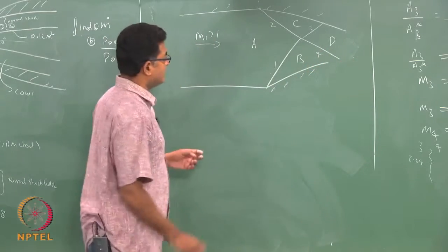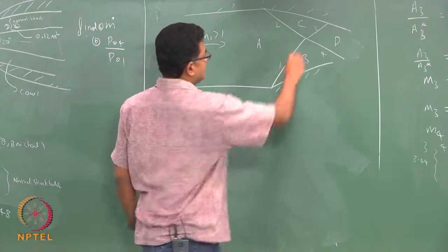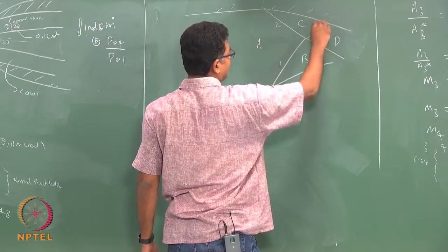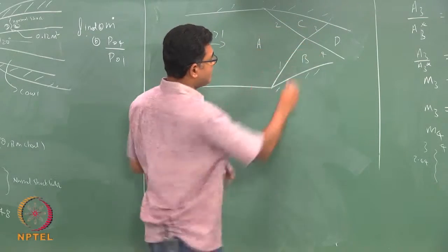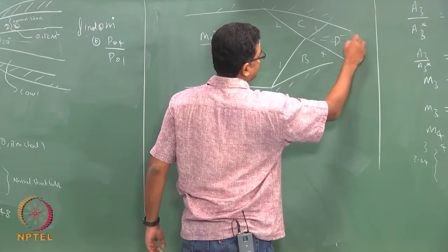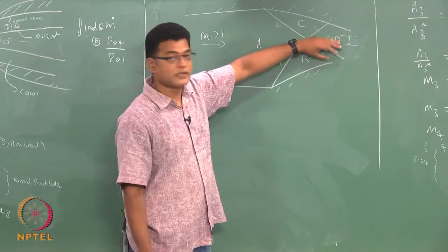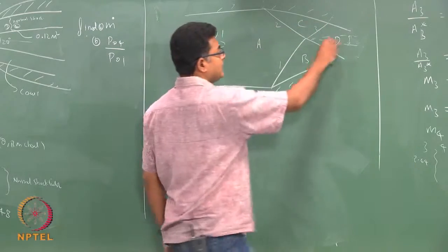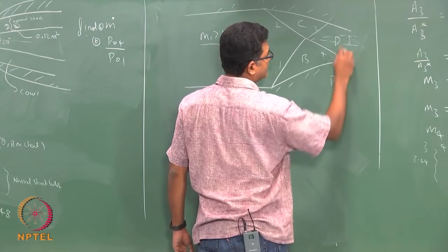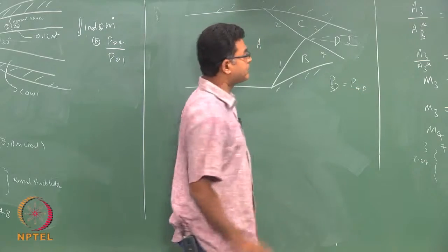This is region A, B, C and D. Okay. So, first reflection is very straightforward, you can do. Then the second reflection also you can somewhat, some of the things are true, but here you will have two slip lines. Okay. So, you have to do it iteratively to get this particular region where the pressure in D, say for example 3D, and pressure along 4D are the same.